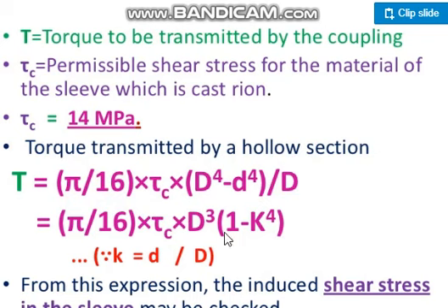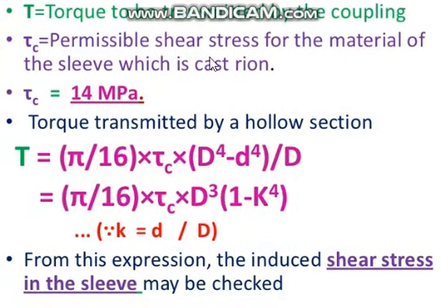This equation we are aware of when we are designing a hollow shaft. From this expression, the induced shear stress in the sleeve may be checked. Here we are not finding the diameter of the sleeve or the diameter of the shaft using this. We are using this equation only to find out the induced shear stress.